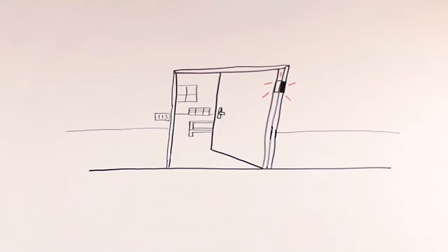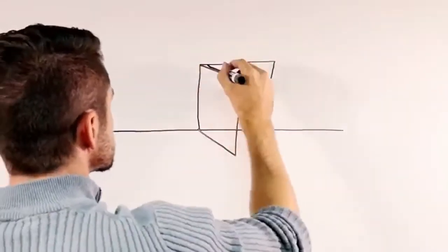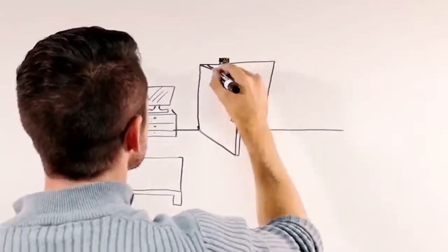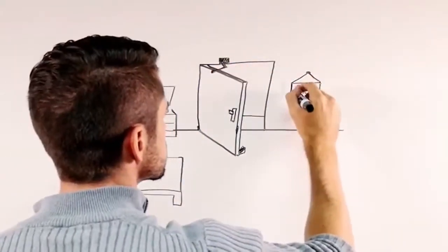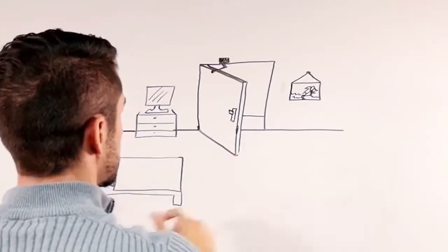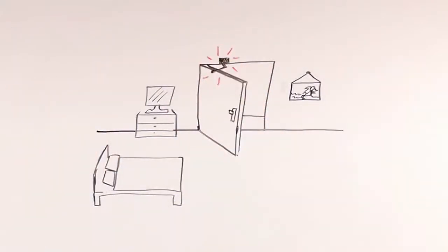Codes determine the required rating for all of a building's components and assemblies. A fire door must be closed and latched during a fire in order to perform as designed and tested. If a fire door is propped open, it will allow the smoke and flames to pass through and is of no value. One of the most important components of a fire door assembly is the closing device.